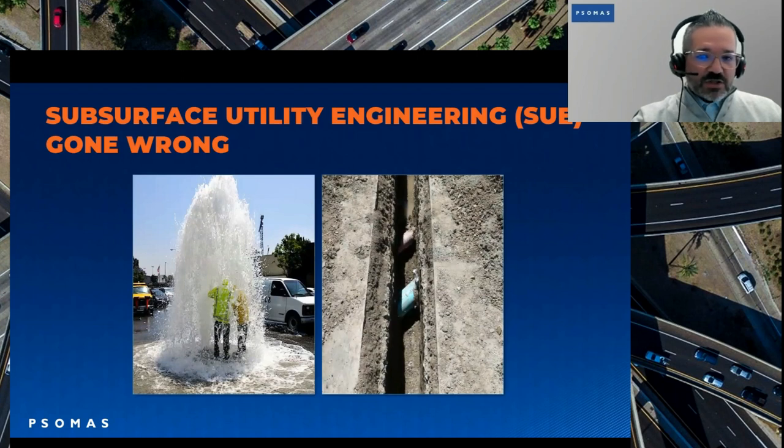And this is where I saw the importance of this ASCE standard and how to implement it. When we first started the project, we were using One Call to do a lot of our utility marking. As you can see from the pictures, it would go out and mark it, and then we'd go out and dig. And like this first picture shows, we struck a water line because they improperly marked where the line was.